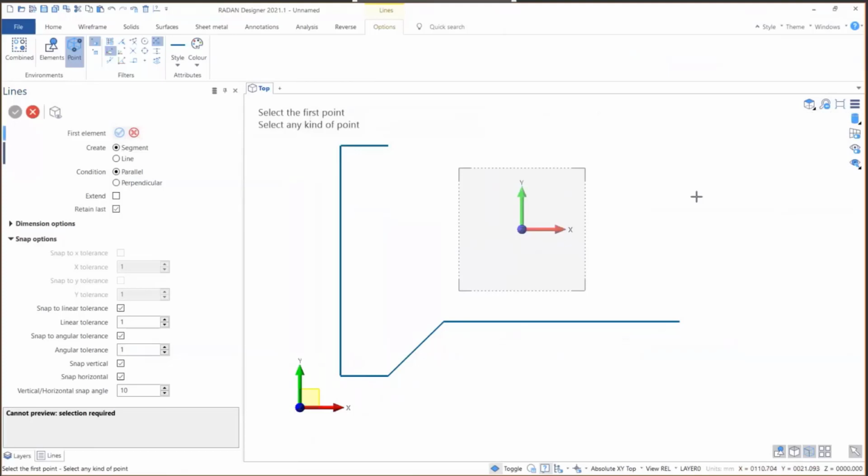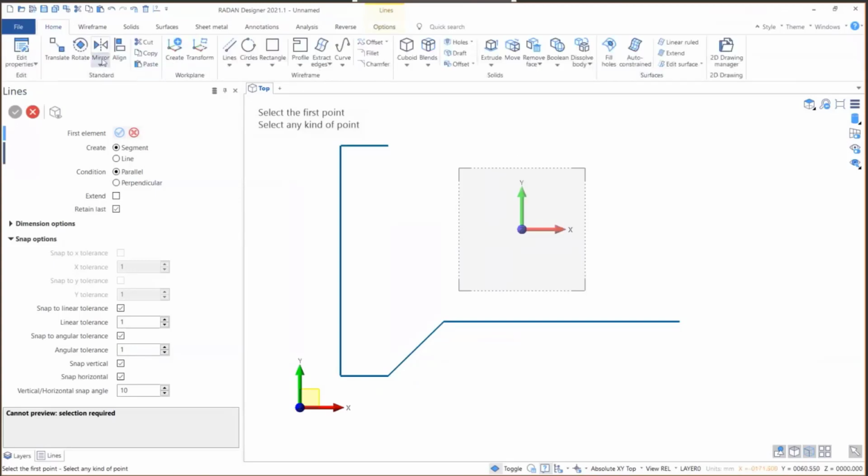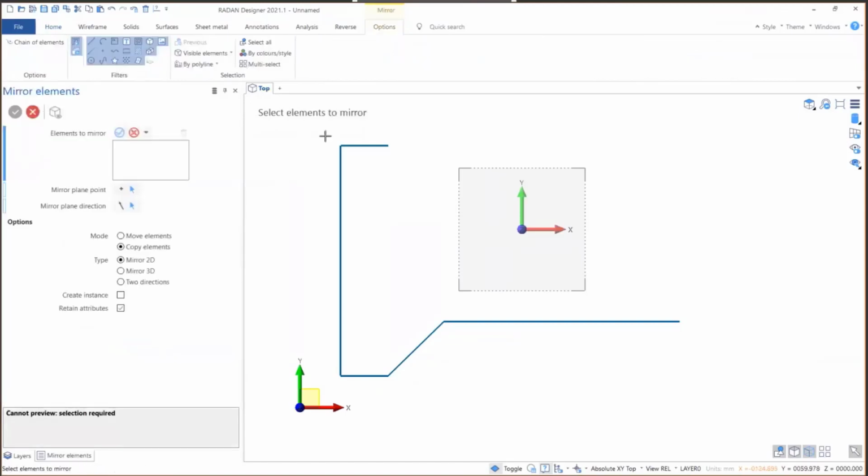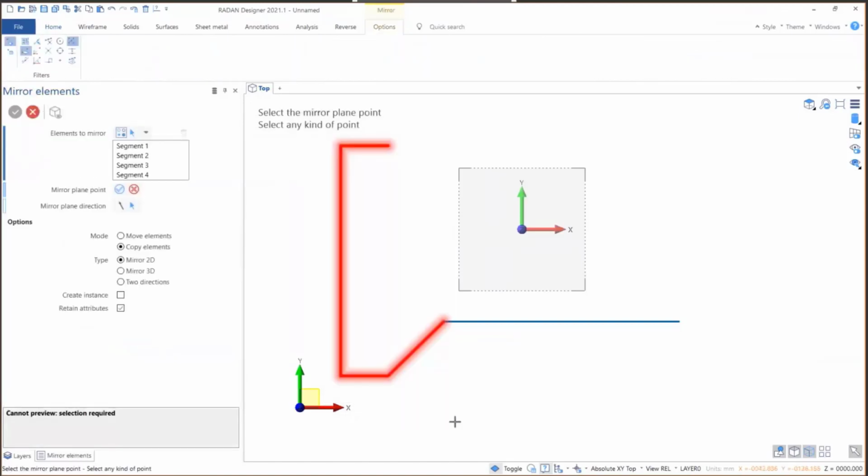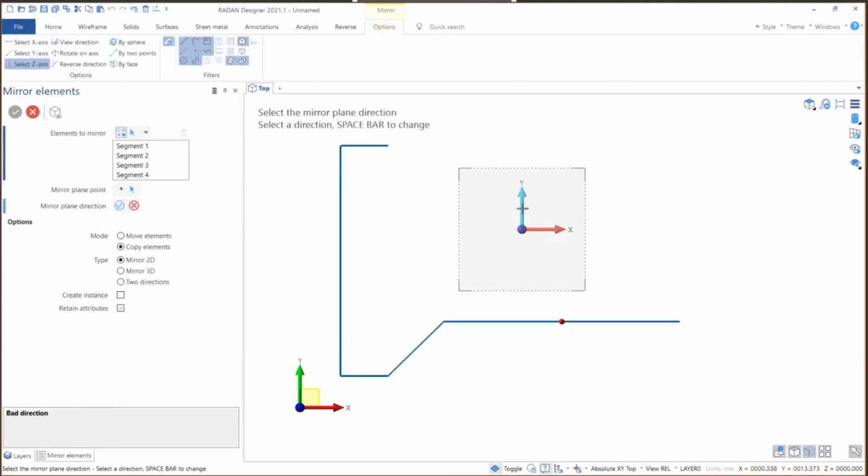Now, when you're producing drawings, it's always a good idea to be looking for symmetry. I know that this part is symmetrical, so I'm going to use the Designer Mirror tool, and I'm going to window around this geometry at the end, and I want to snap, and we'll talk about snap modes as we go, but I'm just going to snap to the midpoint of that and say that I want to mirror vertically about that midpoint. I'm going to right click to accept.